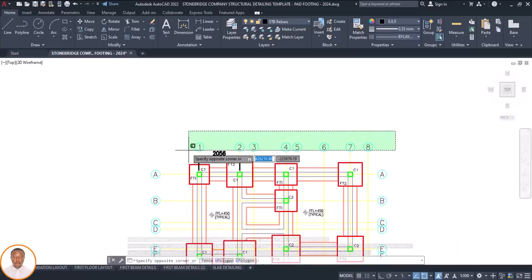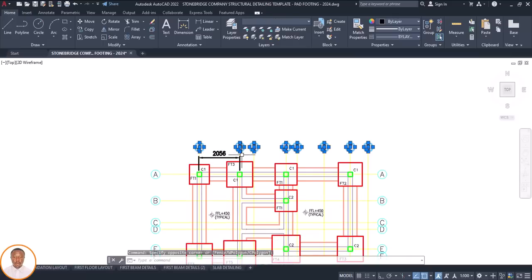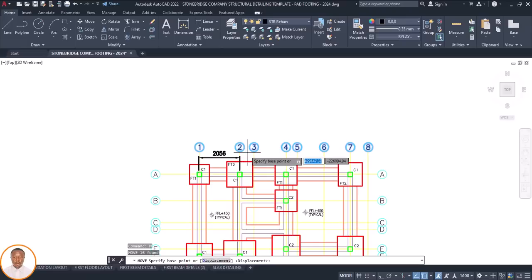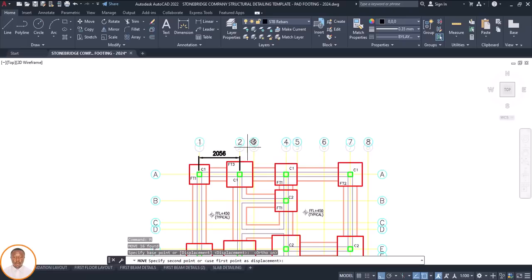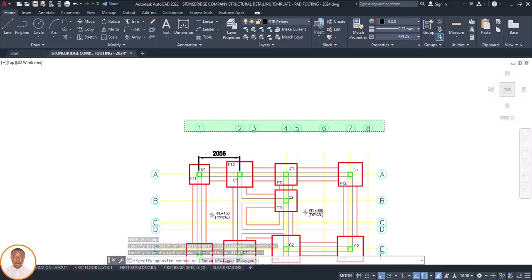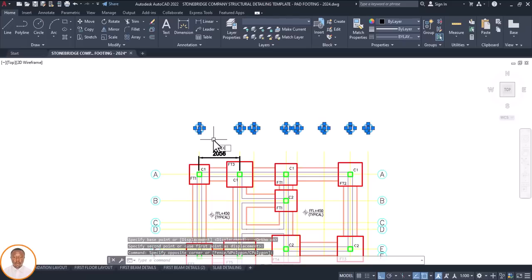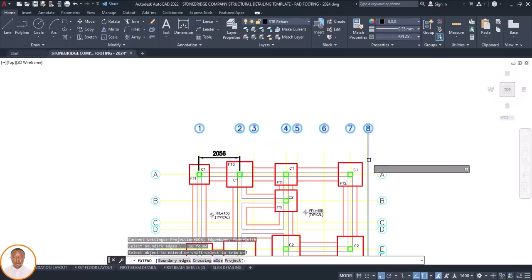So this is how to go about it. Select this one. Once I've selected this one, I will click on M, move. I want to take it up. Make sure my snap is on. Go up, direct. This one is okay. I can do any adjustment later. So I now select all of this. Select this one again. Then EX, which is extend. Enter. I'll come to this place.